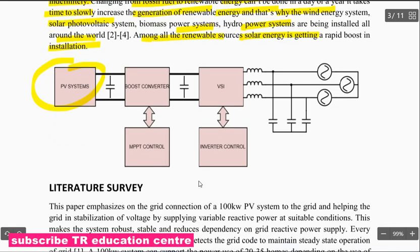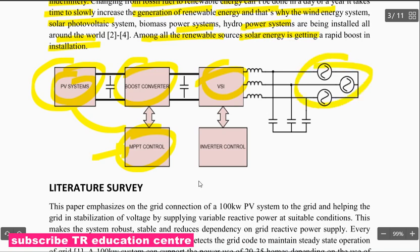There is a PV system. After that, we use a boost converter controlled by MPPT control. We can extract maximum power from the PV system with the help of the MPPT control. Then a voltage source inverter follows the boost converter, which is then connected to the grid.